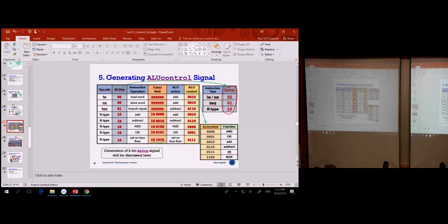Okay, suppose that I pass in two numbers. The first number is all zeros, and the second number is also all zeros. So the processing unit will take the last two digits. Eventually it becomes 0 and 1, correct? Then you add in the carry to get two's complement. So whatever the result, we always add 1 at the end. Your carry in has to be 1 because it is a subtract operation, into the least significant bit.